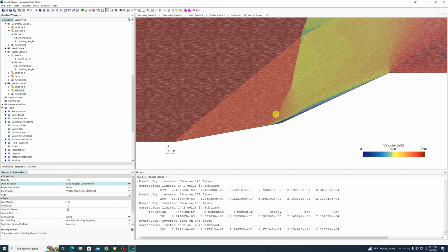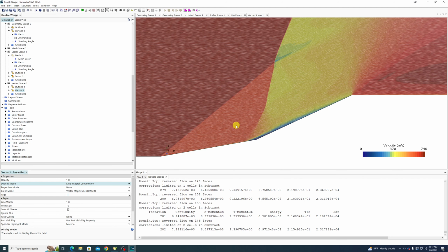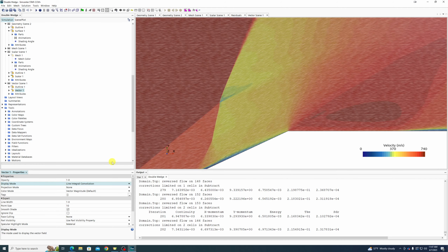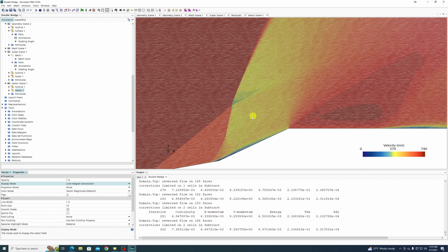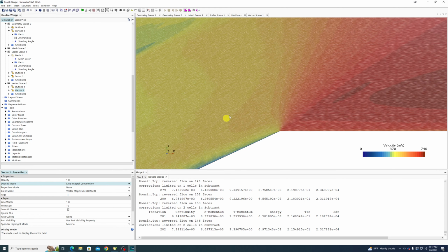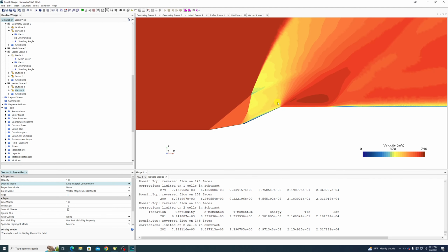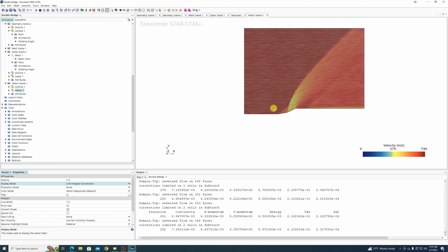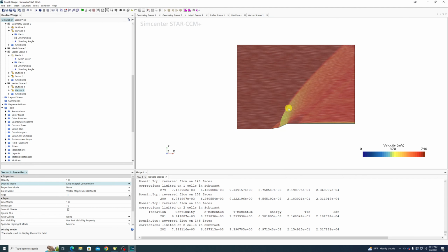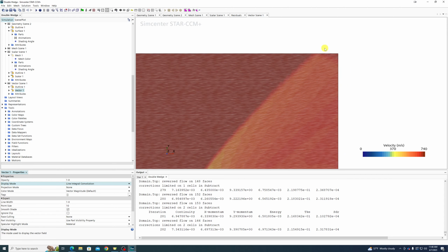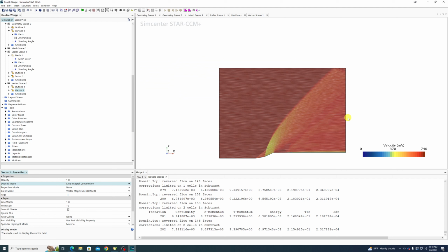So we have a sharp 10-degree turn, and then as it approaches this shock wave, it does another 15-degree turn-ish, but it's not quite straight. And then it also turns as an expansion fan around this corner and extends downstream. And this effect does walk off the top here. That's fine, that's more or less expected. The fact that this interacts with the boundary up here is fine because it's supersonic flow, and this is only going to have effects propagate downstream, not upstream. So this interaction has no bearing on what's happening down here. None.